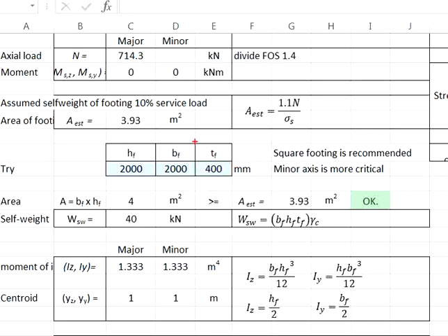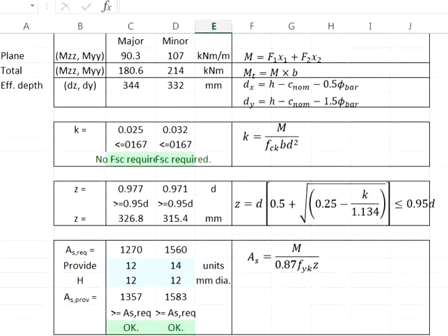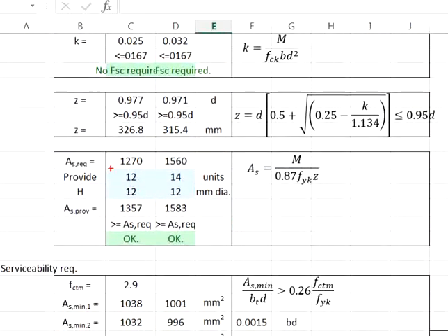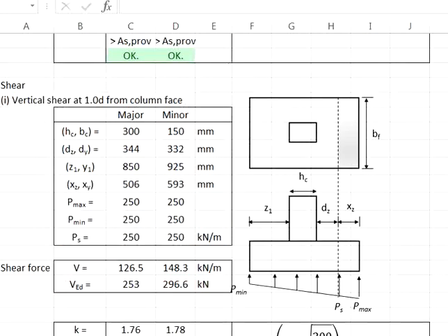At this moment, we are not really concerned about the thickness yet, because later we will need to go through the calculation steps to design for the moment resistance, work out the suitable amount of reinforcement bar to be embedded in the pad footing, and then check the shear resistance of the member. We will need to check 3 types of shear.